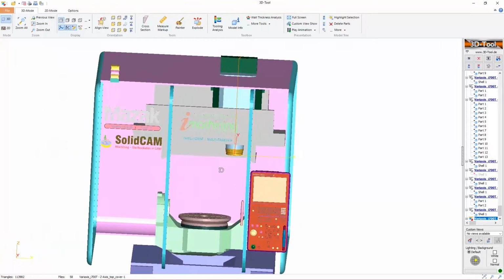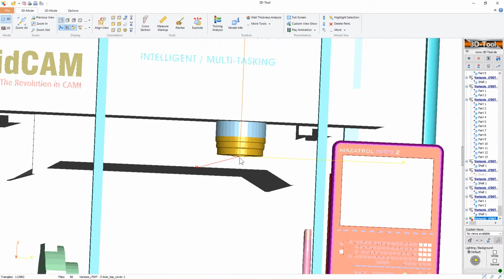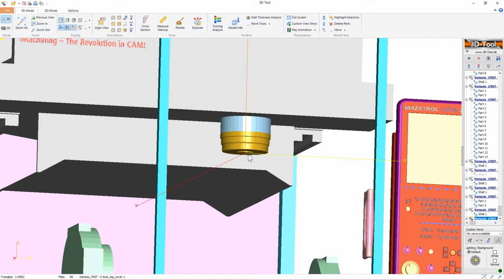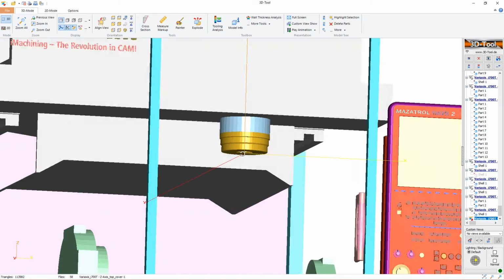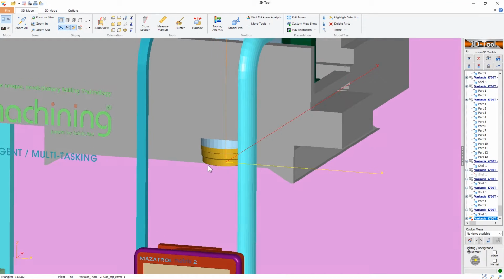You will note one thing here, the spindle itself is located in machine 0. And I didn't mention this, but the coordinate system of the STL files is located in the machine 0, and our spindle itself is located in that point. So I'll choose that this is my home reference point. Therefore, the home reference for all my axes will be 0 itself.